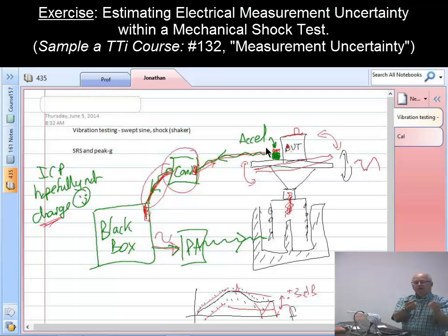If I had my accelerometer on the other side, in that case, the accelerometer is over-reporting the average. The controller will shut down the acceleration a little bit, and I'd be under-testing the device under test. And so for a single accelerometer output, we need to perhaps do an experiment where we run 2 accelerometers and we look at the difference between them to try and assess what the rotation is. It'd be nice to put them on either side of the platform maybe.